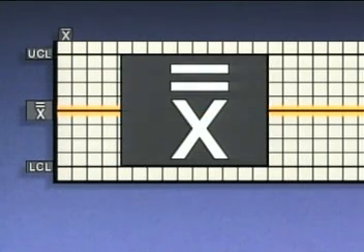The X-bar chart gets its name from this letter and symbol. The X represents the value of the variable being measured in a process. The line above the X, or the bar, is a mathematical symbol that represents an average. So the X-bar chart is used to plot the average of the values taken from the sample group that's collected from a process. An X-bar chart has an upper control limit, a lower control limit, and a process center line. On an X-bar chart, the center line is sometimes referred to as X double bar or as the overall average.